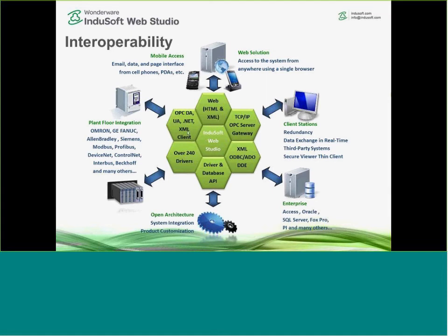We can be an OPC client using OPC DA, OPC UA, OPC .NET, and OPC XML, so we can communicate to anybody's third-party OPC server. We can also be an OPC server for DA, and shortly we'll be an OPC server for UA as well, planned probably third to fourth quarter this year. So lots of different interactions and capabilities in the product. I just wanted to touch on a little bit of those because it'll enter into some of the discussions a little bit later on.